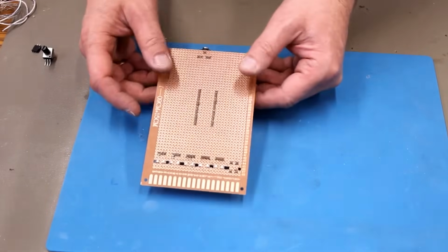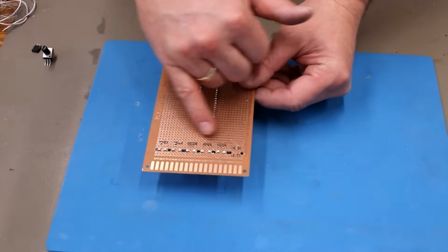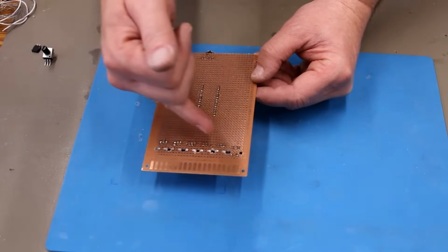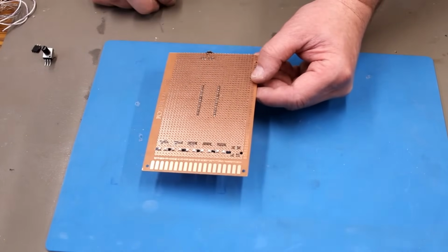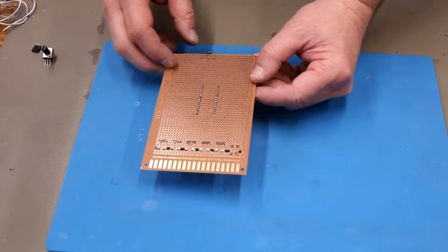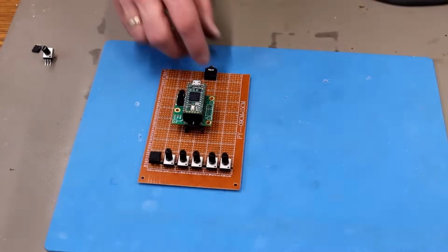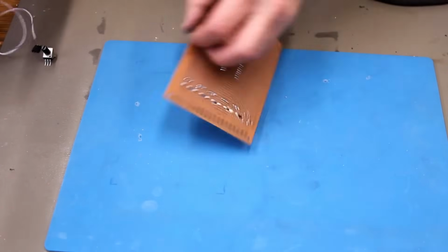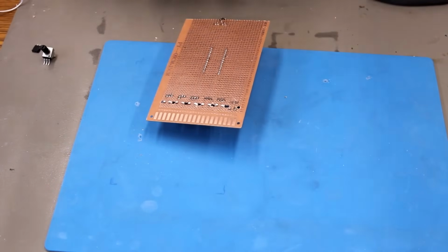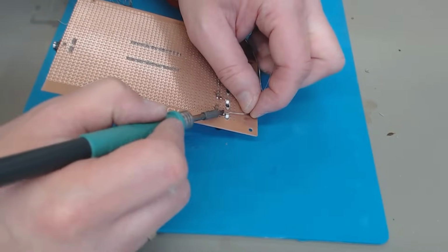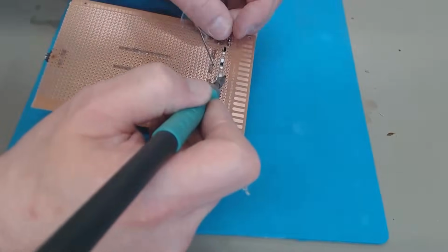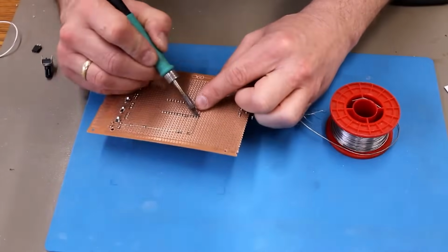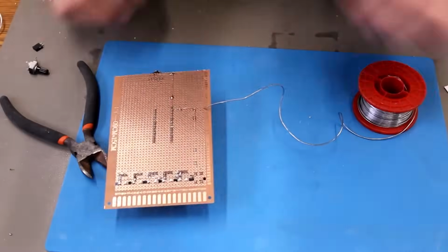For that, we need to connect the power and the ground to the potentiometers all the same. Make sure you use the 3 volts. And then the center pins we're going to connect to the I/O pins. And of course we have to hook up the audio. Okay, so let's start with the ground wire. That's going to be easy. So that's our ground.